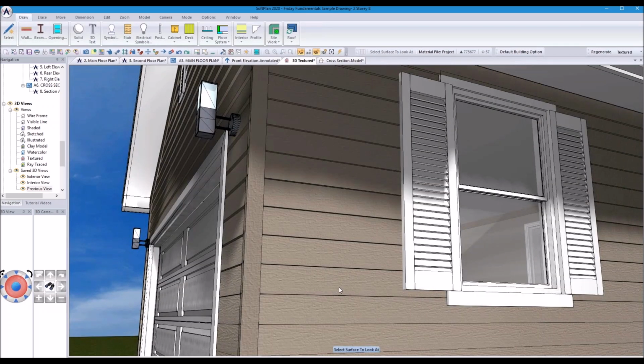So we want you to use the profiles when you're doing wall definitions. And we would prefer you use those over a texture on your 3Ds, because textures are limited. You could put a siding texture in there and you might find one from a particular manufacturer that's the right color and so on. As soon as the customer comes along and says, can we change the color, and you don't have that particular one in your list, then you have a problem.